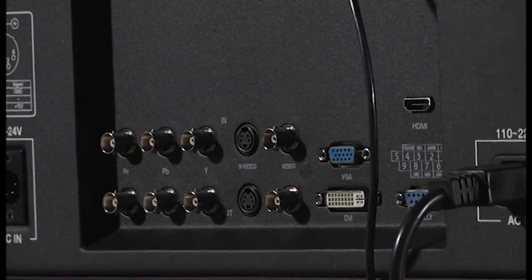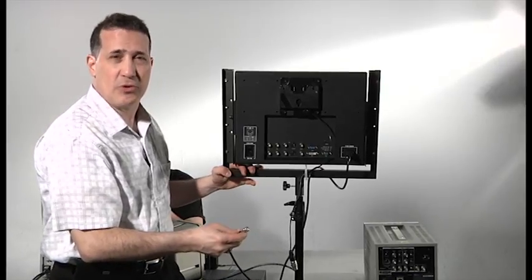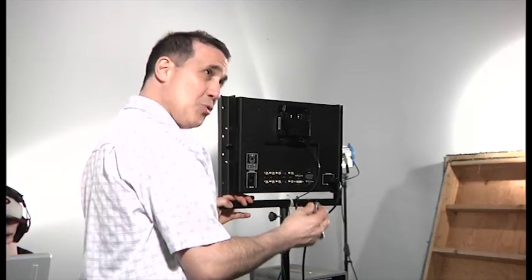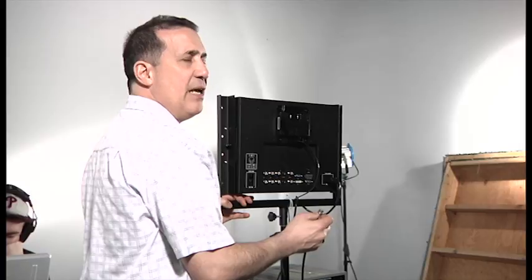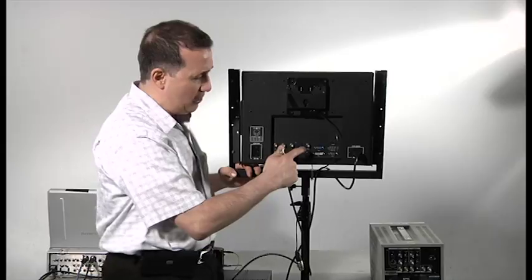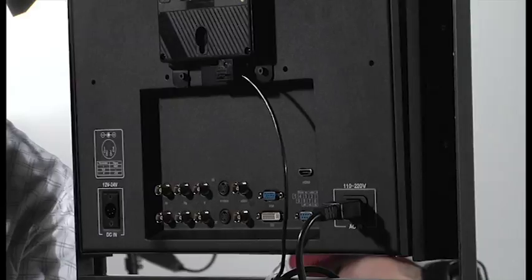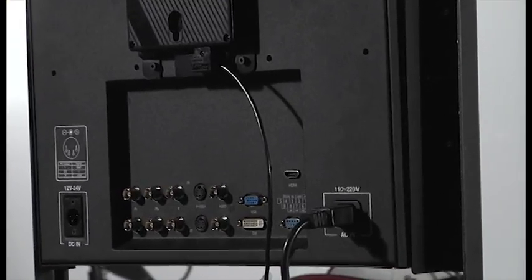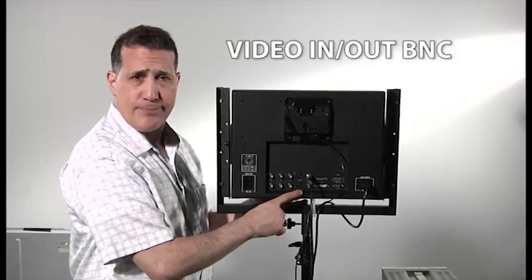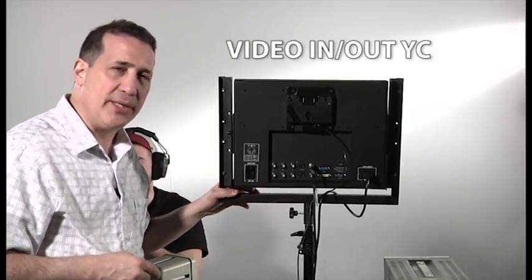The word composite in this case fundamentally means it's a line signal, just like you would use on your old gaming system from 10 years ago, 20 years ago, 30 years ago. It's the actual same signal that's been around since the invention of television. Standard definition, normal, everyday video input is what's considered composite or line. It just so happens we're using a BNC tip in this case, right? It might be RCA, but we're using BNC. This monitor has a video in and a video out in BNC. It also has a video in and video out in YC, which is a separation of luminance and chrominance.